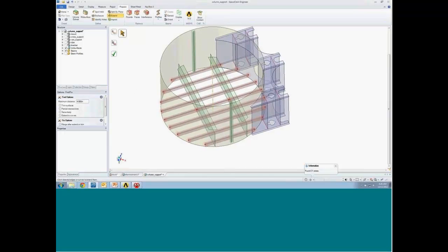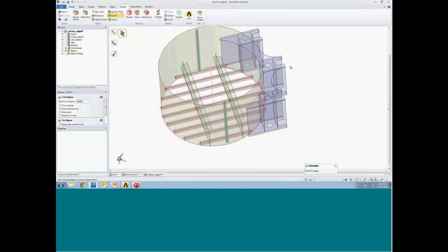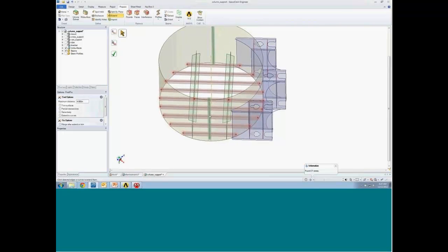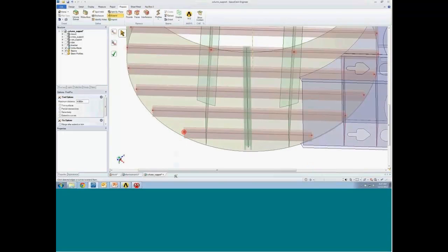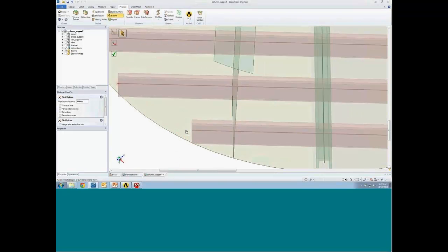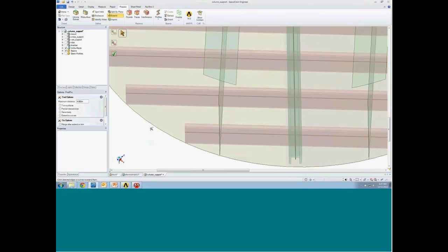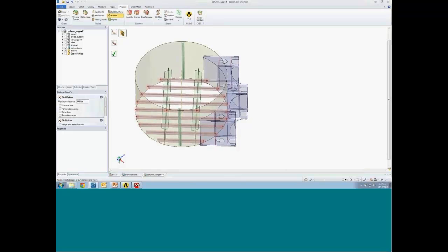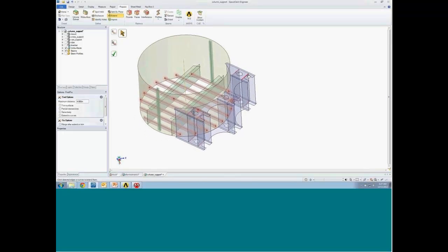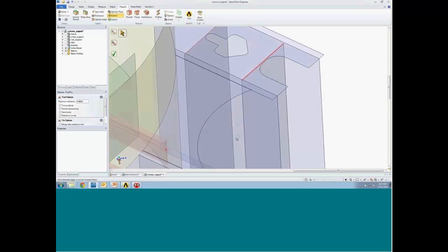You see all the node points of those beam elements and how they extend a little bit too far. If I zoom in on one of them and click that red area, you'll see it kick back over to the right, and now it's coincident with the face of that large cylinder. Similarly, there's certain edges that need to extend upwards a little bit or downwards, depending on your perspective.